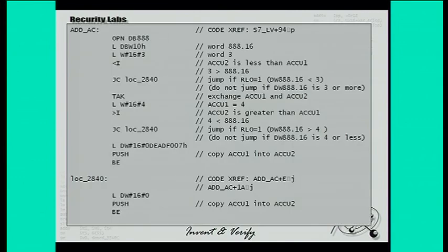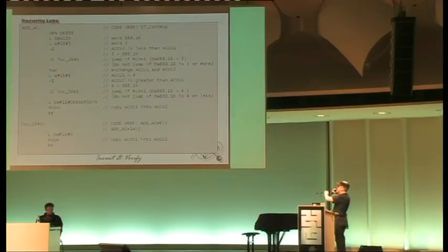And to get you into the mood, this is the actual function that does that. So what it does, we're just quickly covering it so you get a taste for it. The first instruction actually goes ahead and opens a data block with a specific number. If you have that data block in your PLC, you should probably consider looking deeper, because it's not a standard data block, it's the standard Stuxnet data block. Then it takes a value out there, which is the state variable, so it's loading from a data block a 16-bit value at offset 10 hex.